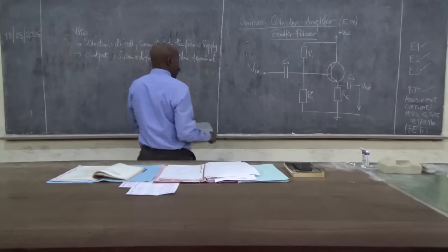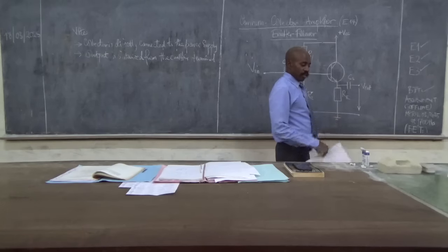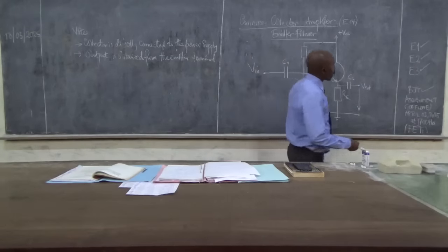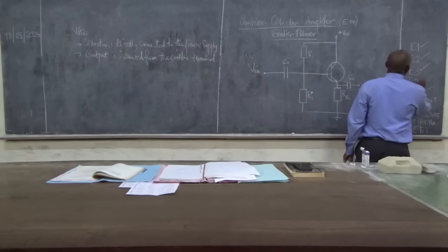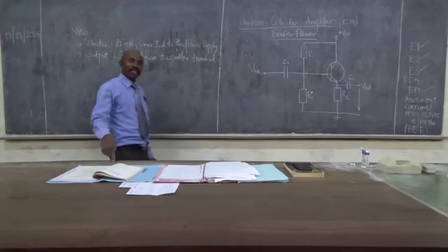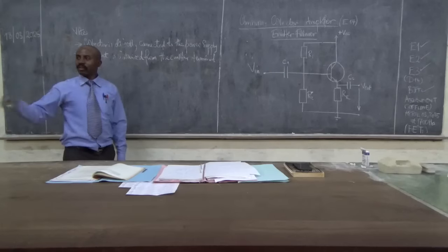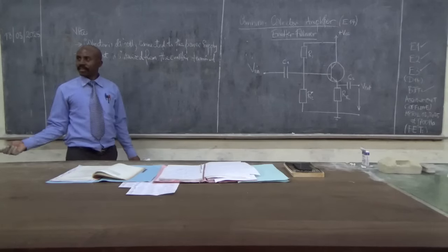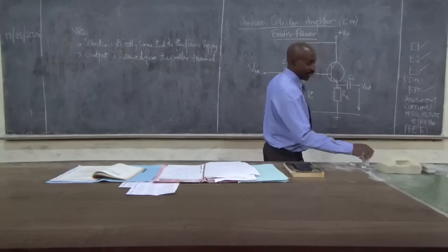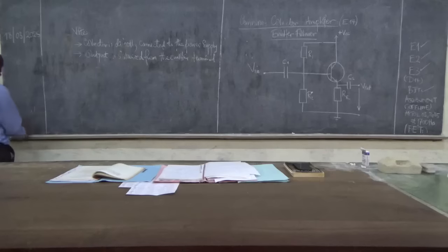But in the multivibrator, the emitters were directly connected to the ground. And they tell you to find those who are doing D14. And they tell you to draw the graphs at the emitter. But the emitter is connected to the ground. And then when some of you get lines, you say we're not getting nothing. You are getting something which is being grounded. And indeed it is that. It's a grounded signal, so it's a straight line.